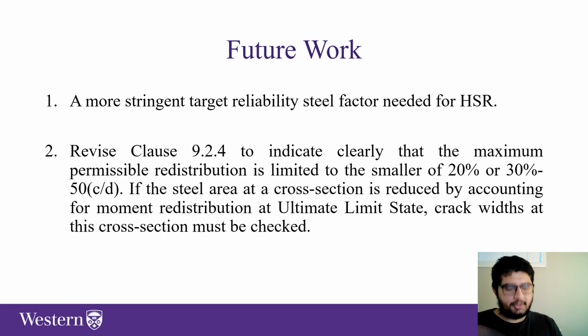Also, if the steel area in the cross section is reduced by accounting for moment redistribution at ultimate limit state, then the crack widths should be checked.